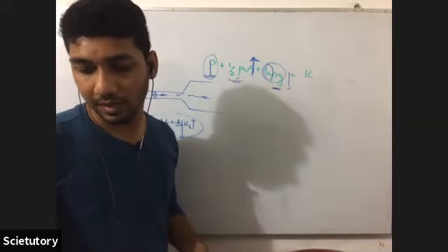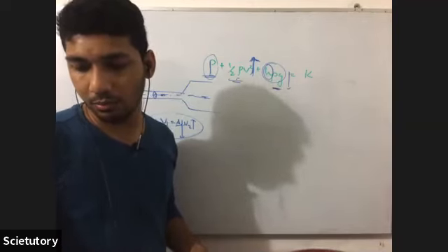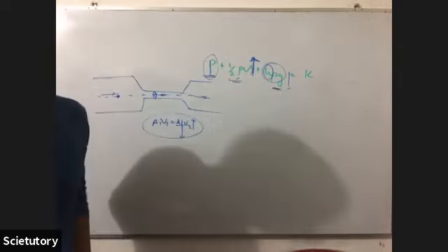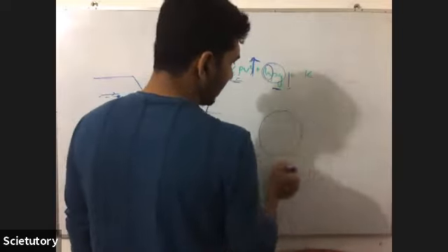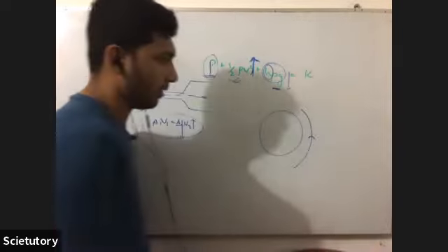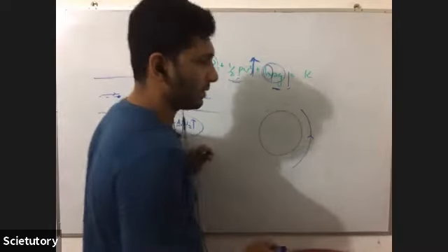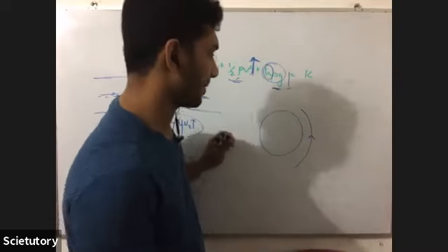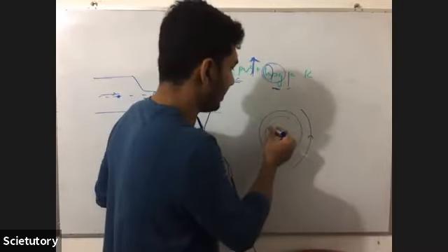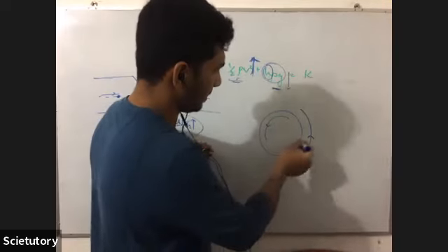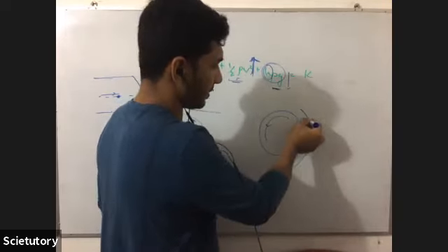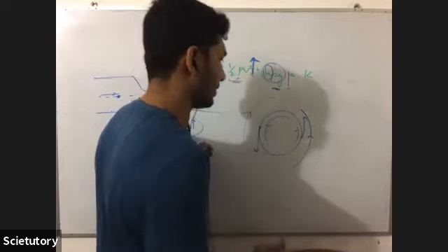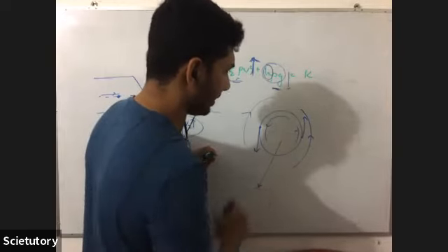Okay. C, deflection of a cricket ball which is moving while spinning. This is an implication of Bernoulli's equation. When you have a rotating ball, there is no change in the streamlines, but when it rotates like this, this side has a tangential velocity in this direction, this side has a tangential velocity in this direction, air has a velocity in this direction, and the ball is moving like this.